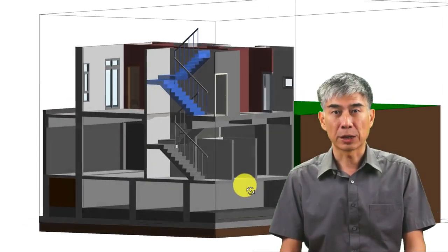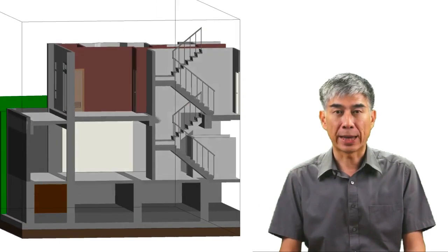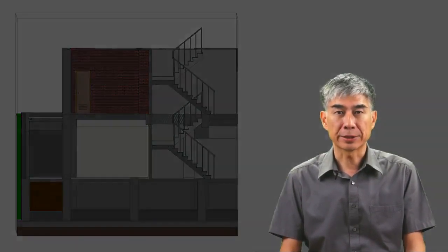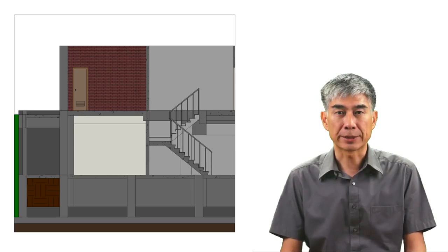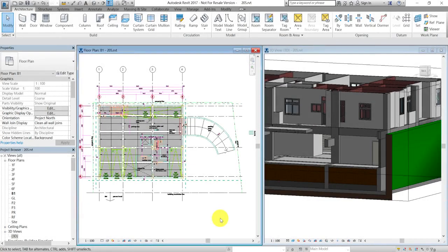In this session, we are going to create the indoor and outdoor stairs between B1F and 1F. We usually create stairs after all structural components. Since we have finished all the structural components in both B1F and 1F, we may start to create the indoor and outdoor stairs in B1F. Let us start to create the outdoor stairs of B1F.